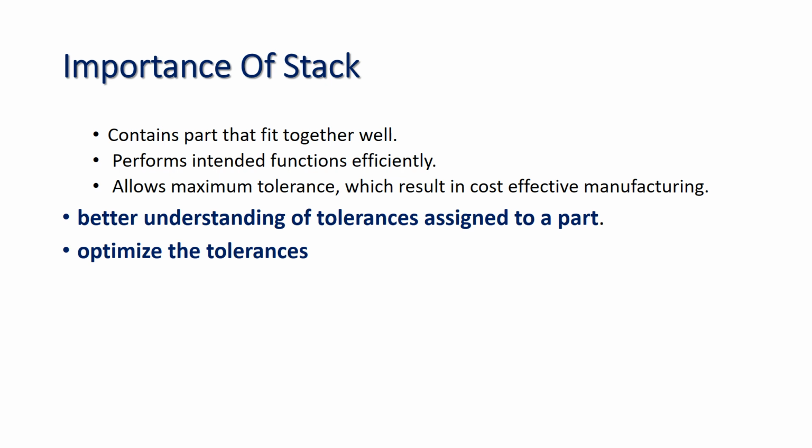Clearance between parts in an assembly can be calculated by using stack, as shown in this example. What is the importance of stack? Because a successful design creates a product, we should understand the nature of the design: will it fit together well, will it perform intended functions efficiently, and do we have enough tolerance to manufacture cost effectively?